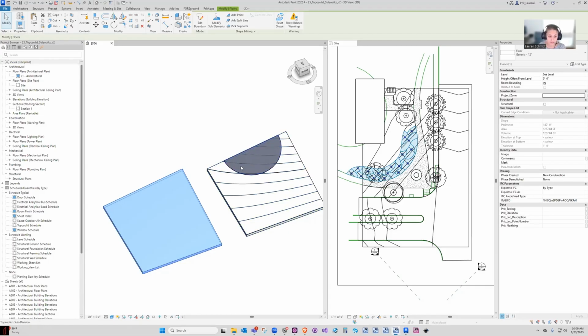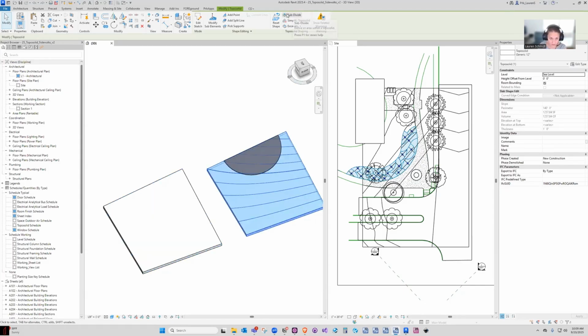The second big reason is that toposolids have subdivision. So I went ahead and dropped a subdivision on here. If you grab a toposolid, you'll see your subdivision is up here. This is particularly important with the new subdivision functionality in 26. Subdivisions give you a lot of flexibility now, so you generally want to be using them. They're a little less flexible in 25. We'll talk about that.